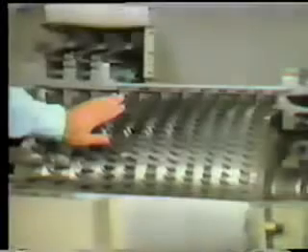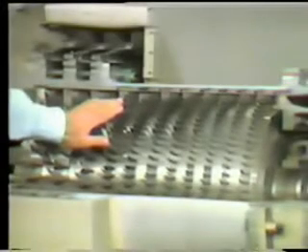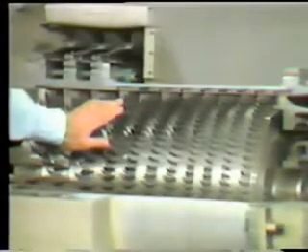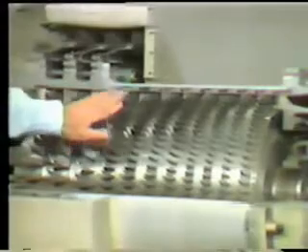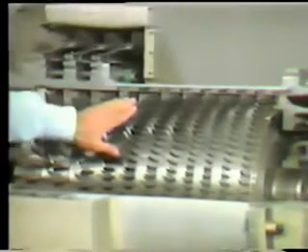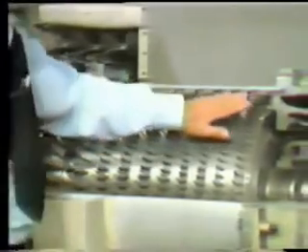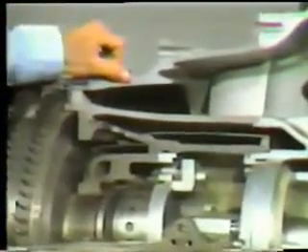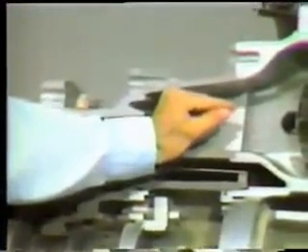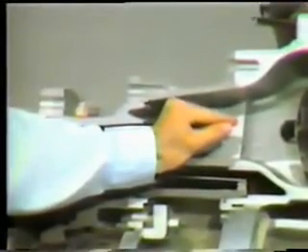To begin the process of energy production, air is first drawn into the compressor, where rows of blades compress the air into an increasingly smaller space. Energy to turn the compressor is first supplied from the external start system until the turbine has enough power to turn the compressor over by itself. After the air leaves the compressor, it enters the diffuser area. In the diffuser, an additional pressure rise occurs.